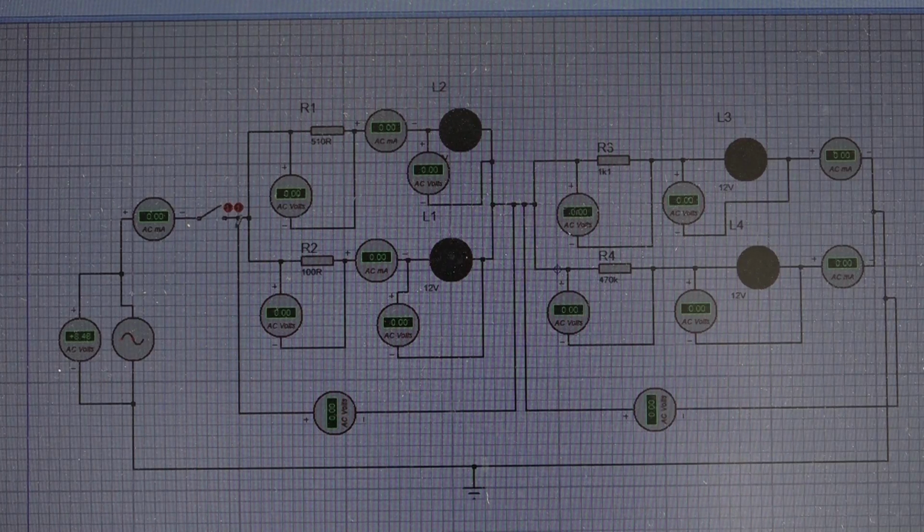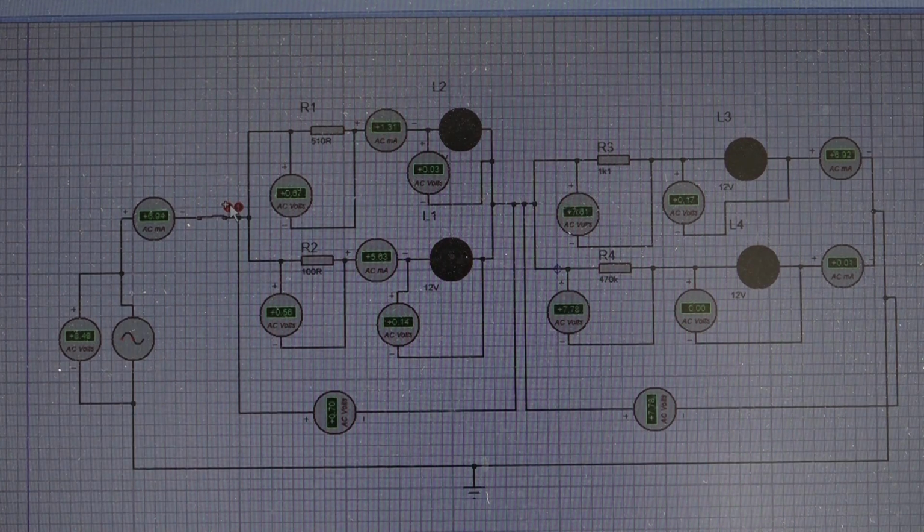So let us turn on the switch and see the measured parameters. You see the measured parameters are completely different from the parameters which we expected. Are we together? For instance, read the measured current at point B. I think it is 60.94 milliampere, while the calculated one is 9.8204 milliampere. You have a very huge deviation.